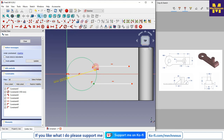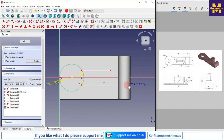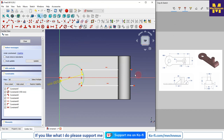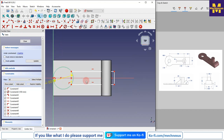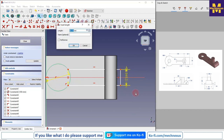I will select this point and my axis, and now I will resolve this conflict. And now I will move it to the outside, and I will join with the line, and I will set it to vertical. Okay, now I will give the dimension 70, so I will select this line and give my dimension 70.